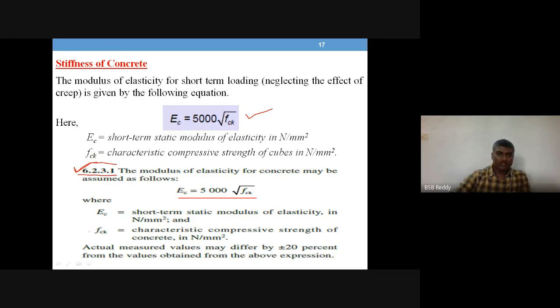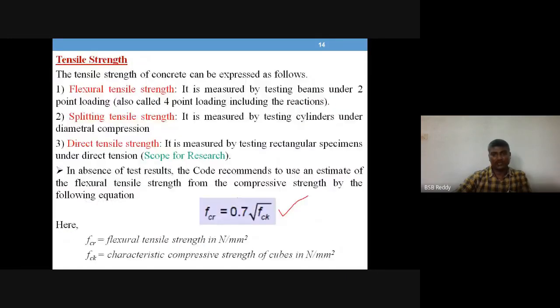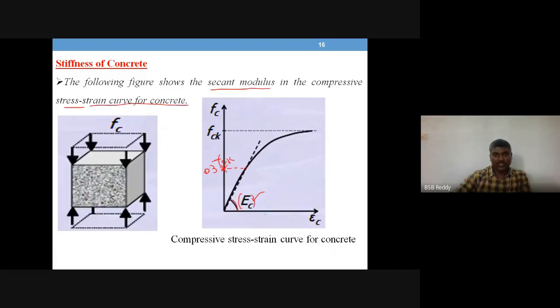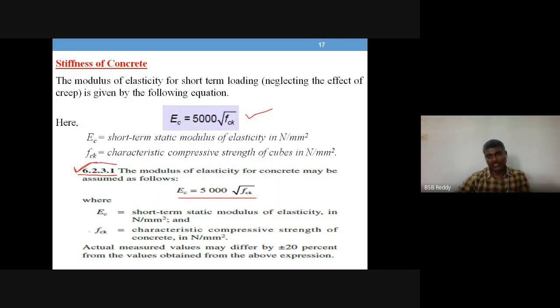Okay, so Young's modulus of concrete is estimated, even any other equation, even the earlier equation that I was telling, like the flexural tensile strength equation. For that matter, any of the content that you can readily refer from the IS code. So if you can keep it handy, the IS code or ready reference. Okay, so IS 1343 that you have to refer, and particularly 2012 revision, not 1980.